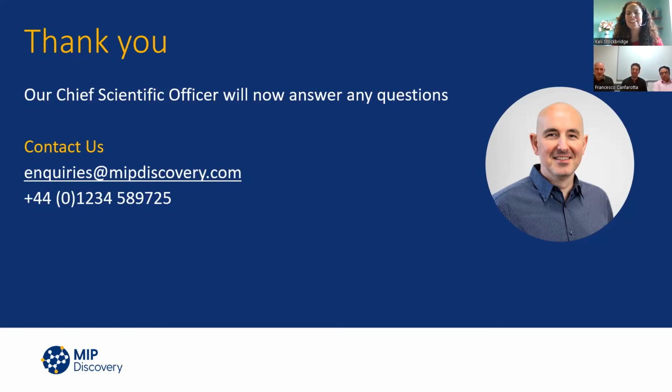Excellent, thank you. The next question is, can nanoMIPs be used in breath analyzers, and are the problems of humid interference resolved in this case? So humidity, in terms of having a binding interaction take place, usually a small amount of water is beneficial, particularly around the target. If we're talking breath sensing in the strictest gas sense, then obviously it will be somewhat challenging.